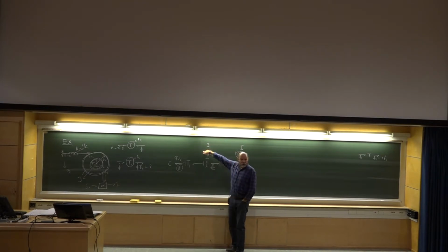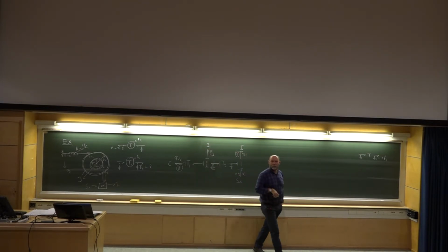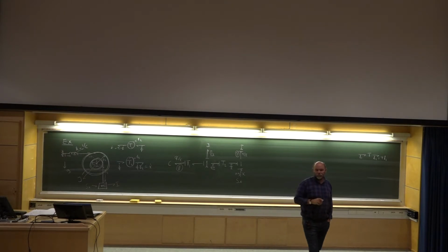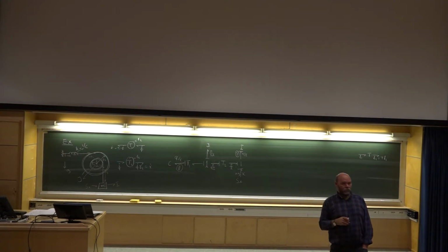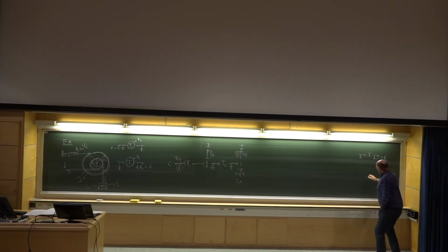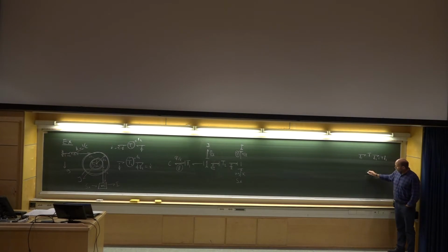What will the effort be on the other side when you have an inertance with the wrong causal form? It's a differential form. That was tricky, wasn't it? Well, what was it? If it's the right one, you have P dot and P over I. If you go the other way, you have something here for the flow. How to construct a P dot?